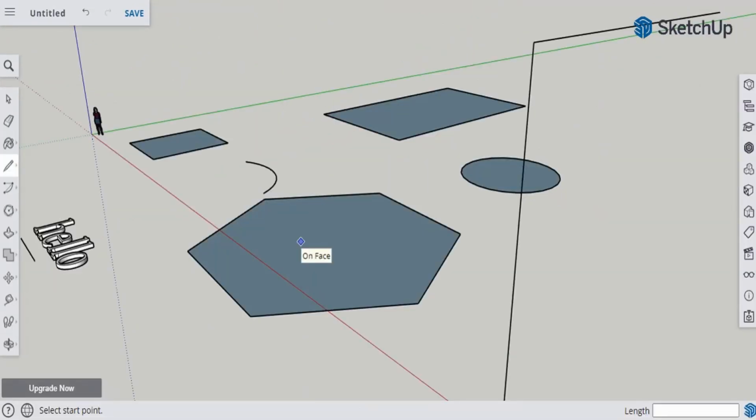Another thing I'd like to mention is what snapping means. Now you may be wondering, what is a snapping? And as you can see here, following my pencil tool, there's a blue circle, a red square, a green circle, and a blue rhombus. And so, colored circles represent vertices and nodes. Squares represent points on sides, and rhombuses represent points on faces of the selected area.